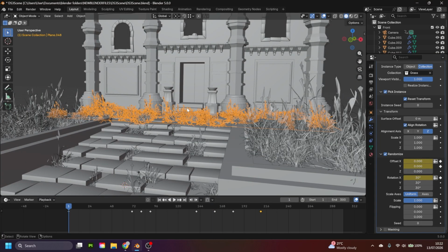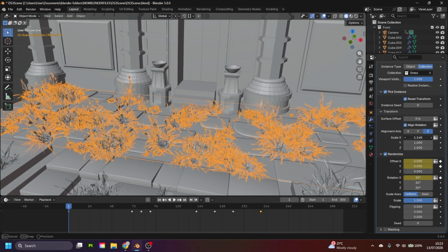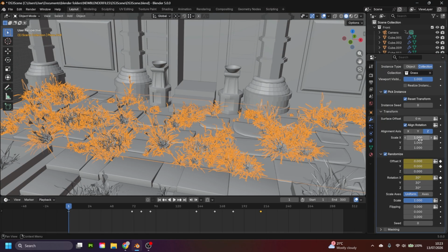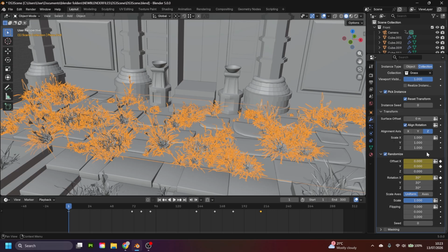If I want to make it more intense, I can just up the amount at each keyframe here, or shorten the whole thing, maybe duplicate it over. I also don't think scaling in the Y and the X really makes sense for the plants, so maybe just in the Z. I'm going to need to do a bit of experimenting with this, but I think a little bit in the Z as well will make it look cool. So I'm just going to do that one more time.